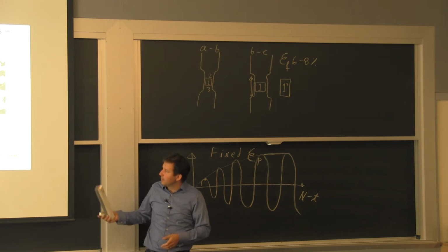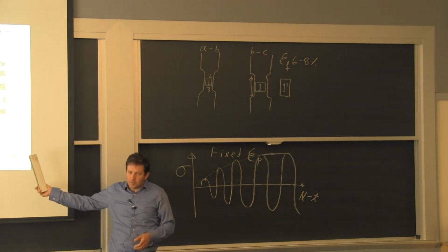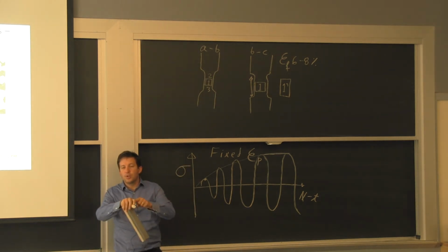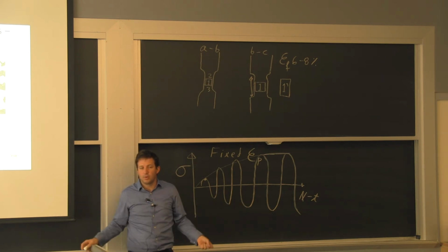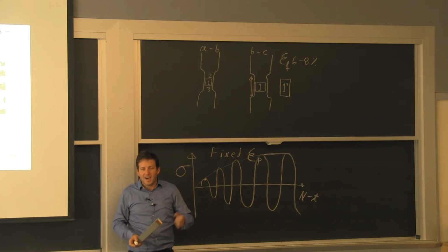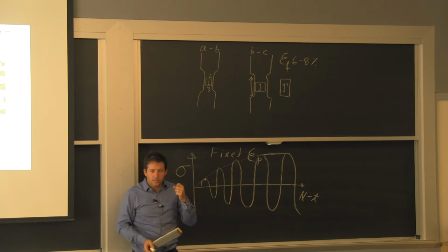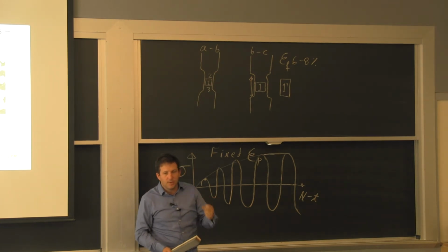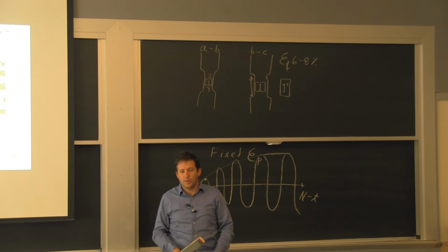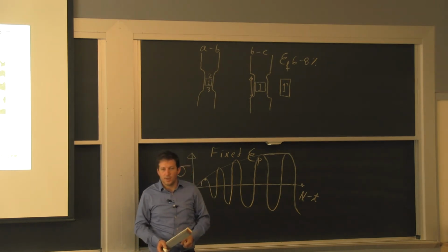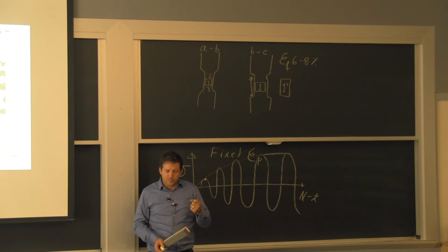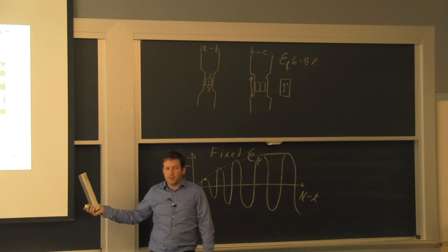You would have a similar effect if I just pull on the material at ambient temperature. When I do cold rolling at ambient temperature, I beat it up. Okay, I'm getting the steel, say, 3-4 times stronger than it was when I started out of the mill, but I'll eventually also reach a stable dislocation structure.